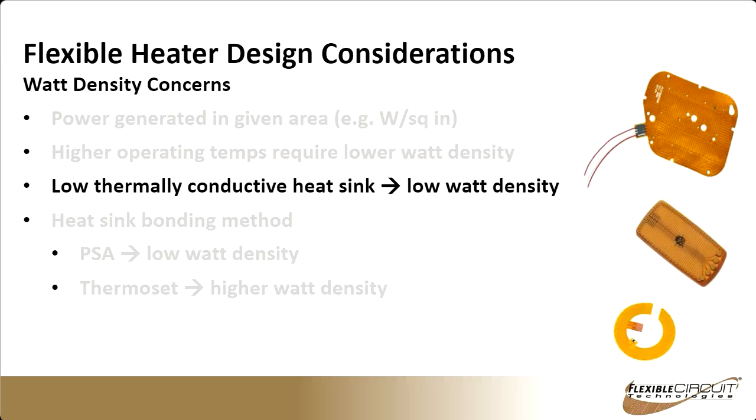If you have a low thermal conductivity material like plastic, you're going to need a lower watt density, and it stands to reason because it's not going to be able to pull that heat away from your heat traces as quickly as something else would.